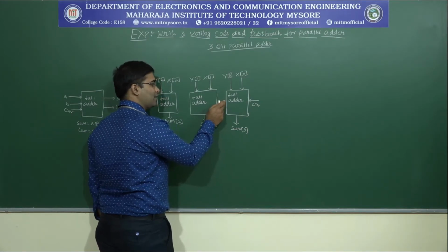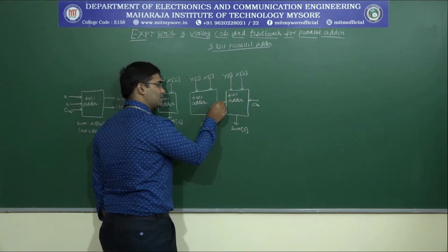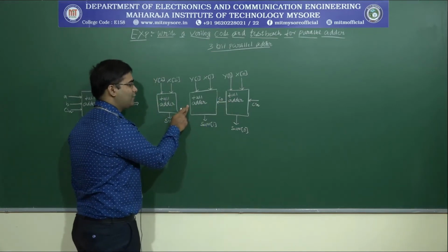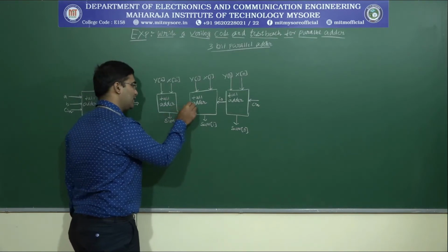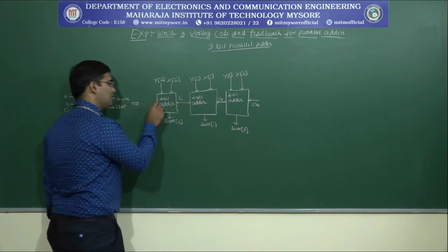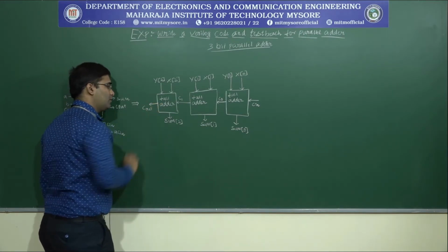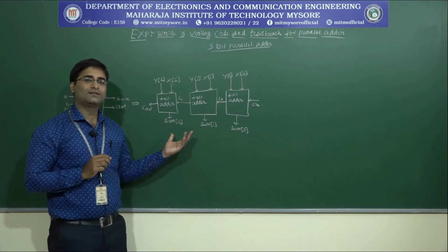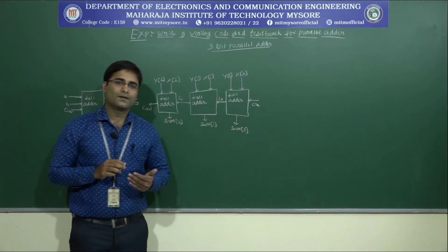full adder, is connected to the input of the second full adder. Let us define this as C0, and the output of the second full adder is connected to the input of the third full adder. Let us define this as C1, and we do have the output, which is Cout. So this is the block representation of a 3-bit full adder, and we will write a Verilog code to this